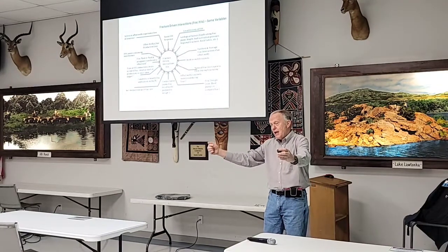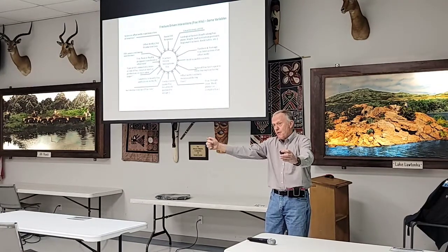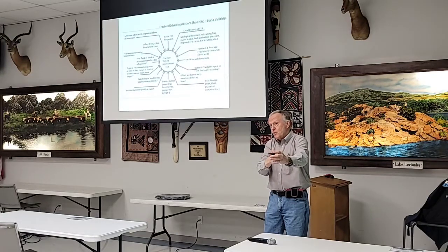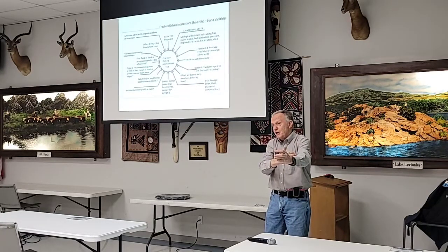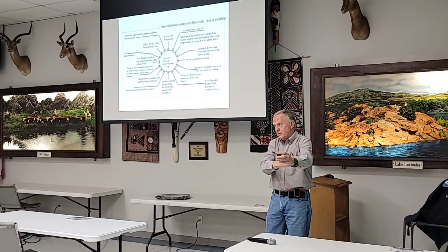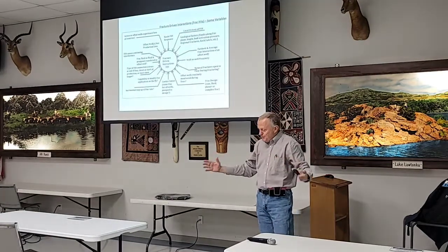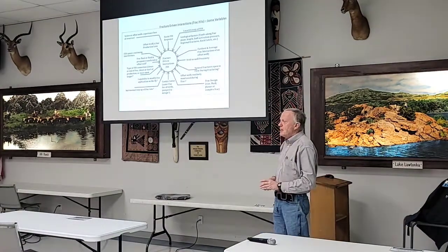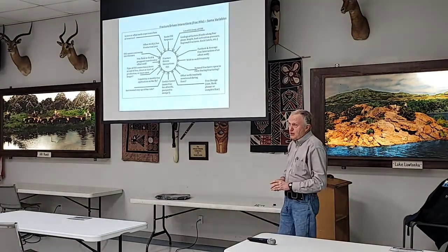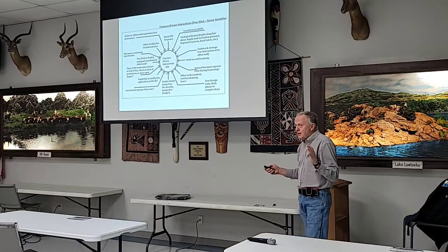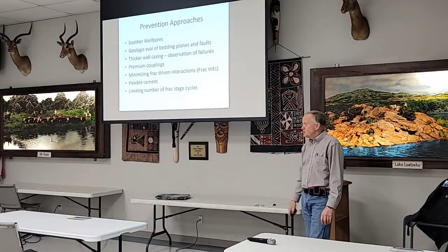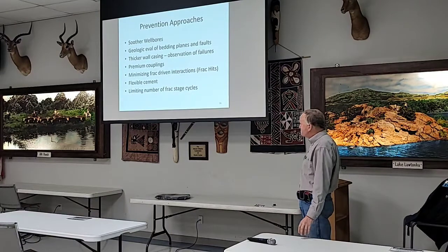But don't line your frac direction up, your perfs along your frac direction, don't line those up with the fracture initiation points in the old well. You minimize damage when you do that, offset them a little bit. And there are some areas that are prone to frac hit damage, there are some areas that are not. But these are just a lot of little different things that we get into in what we're seeing.